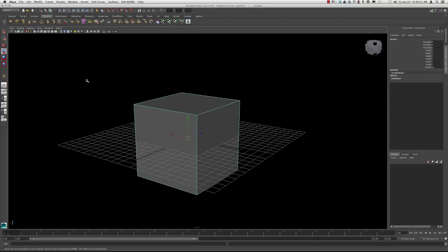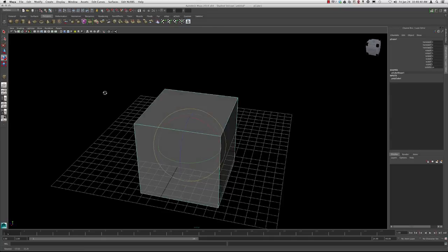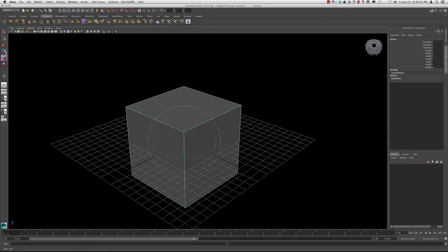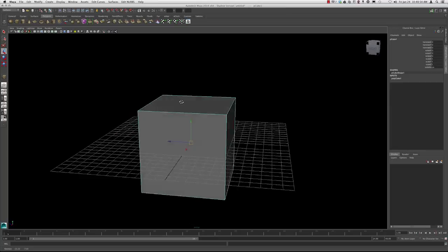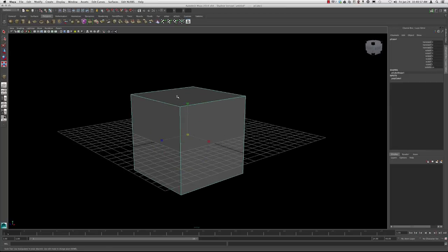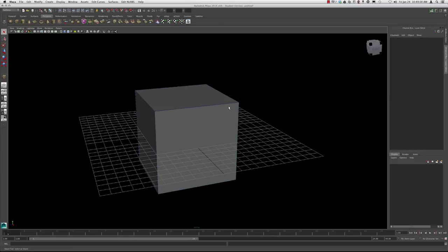This will make more sense as we get further into this. But if you look up at the toolbox, you can also see that when you are toggling between W, E, and R, the toolbox is displaying the tool that's being selected. So in this case, the move tool, the rotate tool, and the scale tool. It's the same thing as going up and clicking each one of these, but it's not as effective to have to go up every time you'd like to make a translation. That's what these 3 keys are essentially for. And it's located pretty nicely. On your left hand, you're going to have your hand on the Alt key anyway. So these are here for you to toggle between, and then the Q, like I said earlier, will go back to selection mode.